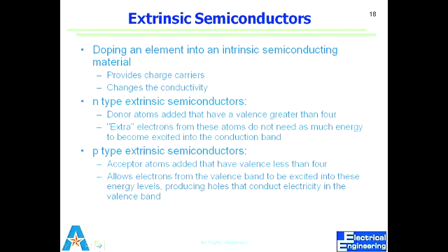There is a different concept for semiconductor materials called mobility. Mobility is important, not the conductivity. Conductivity is more relevant for metals, where we have the notion of Ohm's law: the more voltage we apply, the more current will flow. There's no similar thing for doping in semiconductors. If we dope them too high, mobility goes down because of collisions with the lattice, the static atoms. Make sense?